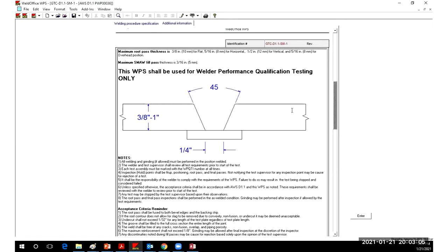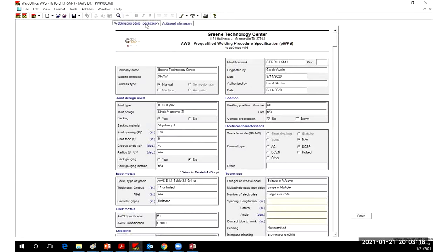If somebody wants an AWS D1.1 pre-qualified WPS, I've got one for shielded metal arc welding, gas metal arc welding with 9010, and flux core with E71T1. For me to change it, or to make one with your letterhead on it, it's a 5-minute ordeal, and that's it. So if you need help, just so you have one to do your own welder testing with, do it. But I would ask that if you want a WPS to do the welder testing, you tell me that you also have a code in your possession. Because that's really all part of it.